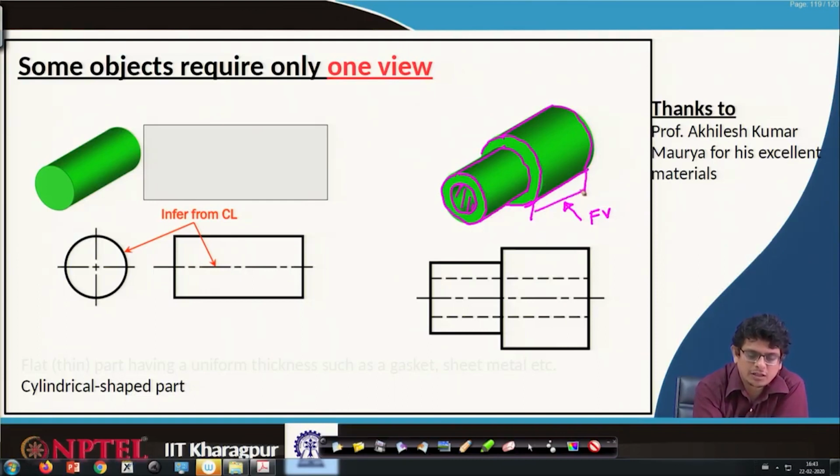This much portion we will see as a rectangle. So, if we are drawing this portion for the front view, it indicates this maximum diameter cylinder. This part, let us call it part A. Because it is a cylinder, we always have long dash, short dash, long dash, short dash, and so on. Now, this B part, the step 1, has a lower diameter and is symmetrically placed around that axis.